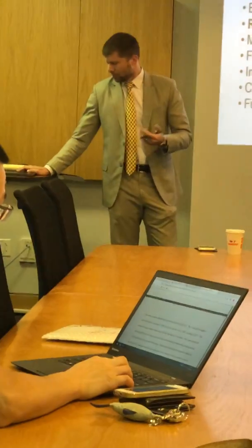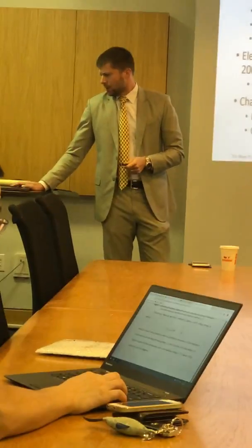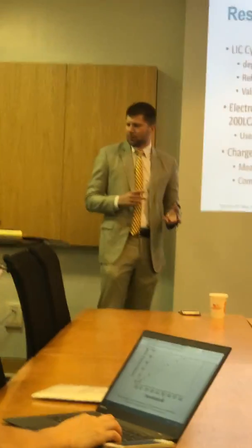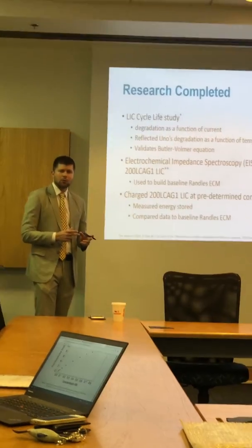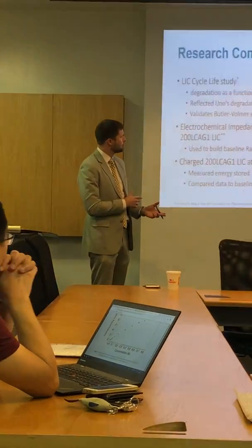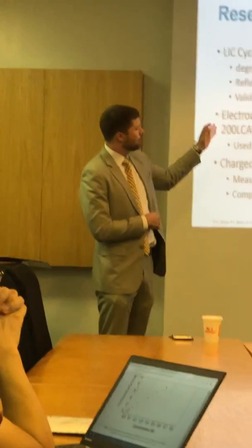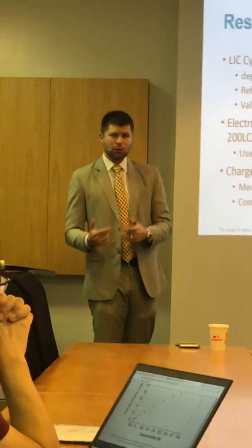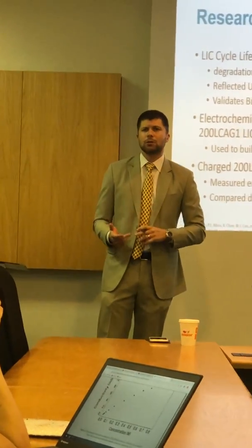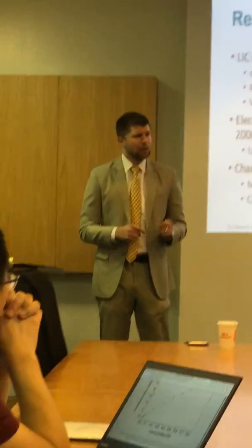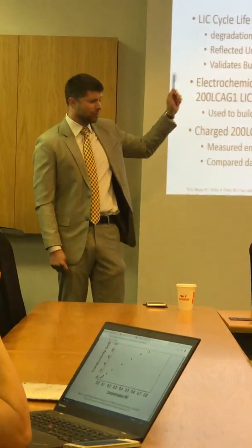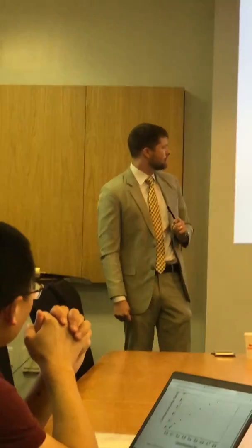All right, so next I'm going to give you a summary of the research I did, which we'll get into in more detail in a minute. First of all, I started with my own study on lithium-ion capacitor cycle life, and I found that Uno et al.'s relationship with different ambient cycle temperatures has the same impacts as changing the cycle current. So there's some proportionality between the ambient temperature of the cell and the cycle current, which the Butler-Volmer equation predicts for us, and we're going to talk about the Butler-Volmer equation a lot later on in this presentation.